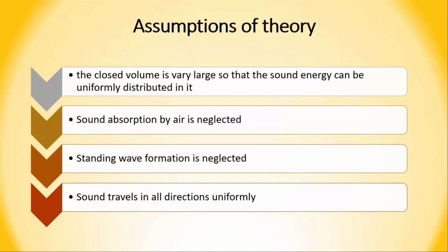The first thing he assumed was that the volume is very large, so that there is a uniform distribution of the sound energy. This theory is applicable in the case of a large volume of building. छोटा सा room है, right? So for a small room, we cannot apply this theory.